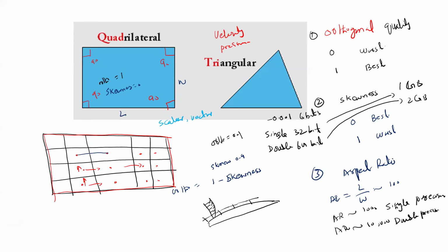The line joining them decides at which point we solve for these vector quantities. Now imagine that we have large cells on a curved boundary. What is going to happen? Let's see, this is our curved boundary here, and we have one cell with a very small height.